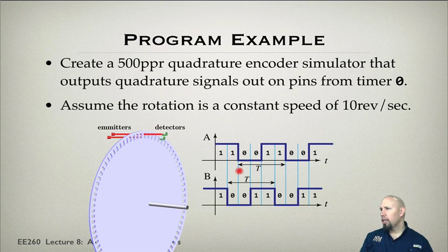And in quadrature, these 2 signals are out of phase. Okay, so one turns on and the other turns on, or this one turns off and this one turns off a little bit later. Okay, and so we saw these things working with optical encoders. We see these things in working with motors. It's a simple way of encoding data, encoding rotational information using digital pins, digital signals. Okay, so that's what the encoder is all about.